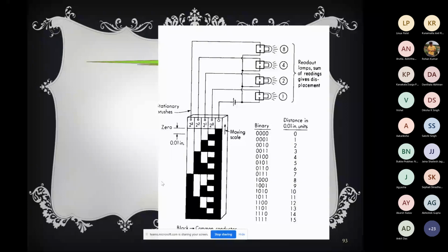In a DC motor, a DC servo motor, we have the mechanism in the lab. Whenever we use the computer and we want to measure the angular displacement and take a control action out of it, we use the optical encoder. Basically it is a shaft rotary optical encoder, and you will see a bus coming from the encoder, a bunch of many wires, 8 wires or 16 wires, connected to the interface with the computer.